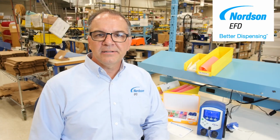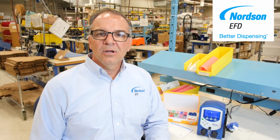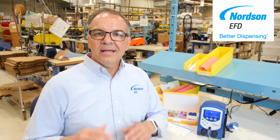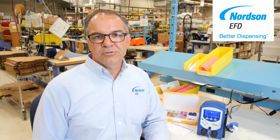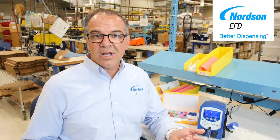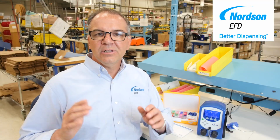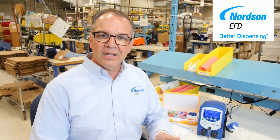So how do you choose the right dispensing tip for your application? When you're making a dot, take the diameter of that dot and cut it in half. That's going to give you the idea of the dispensing tip you should use. When you're making a stripe, take the width of the stripe and cut that in half. And that's going to give you the idea of the tip you'll need for that stripe.